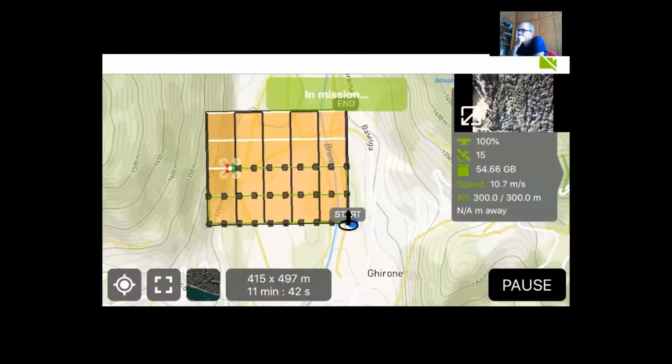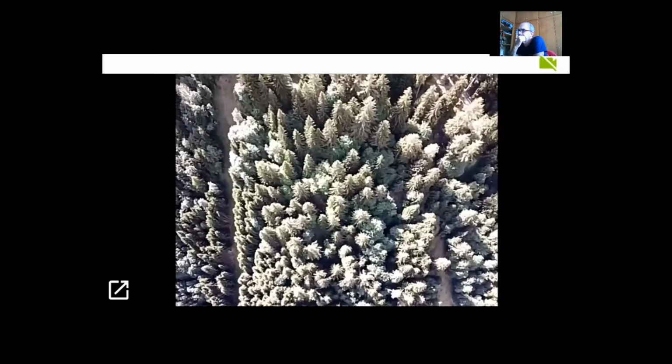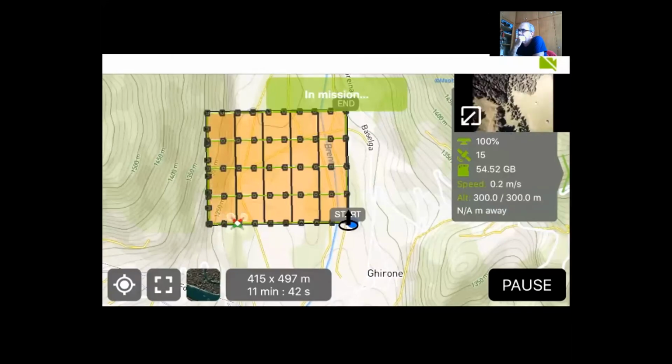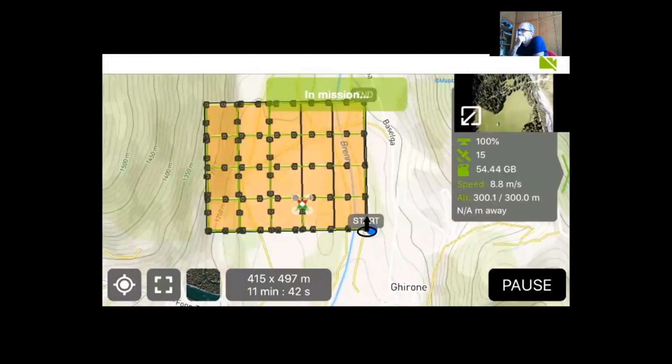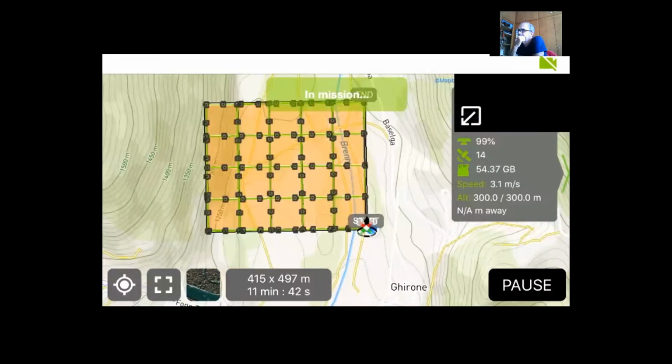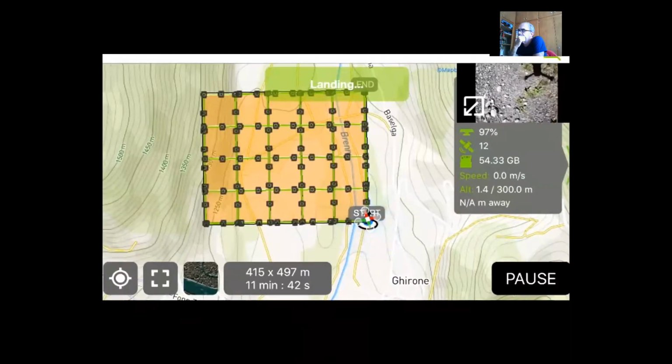During the flight, you always have to keep an eye on the phone and check the velocity. The velocity must be somewhat constant, between 30 and 40 or 50 kilometers per hour. If it is too windy upstairs, the drone might not manage to continue the mission. The drone might also have a software problem. You might have birds in the sky. You always have to keep an eye on the situation, and you have to always be very careful.